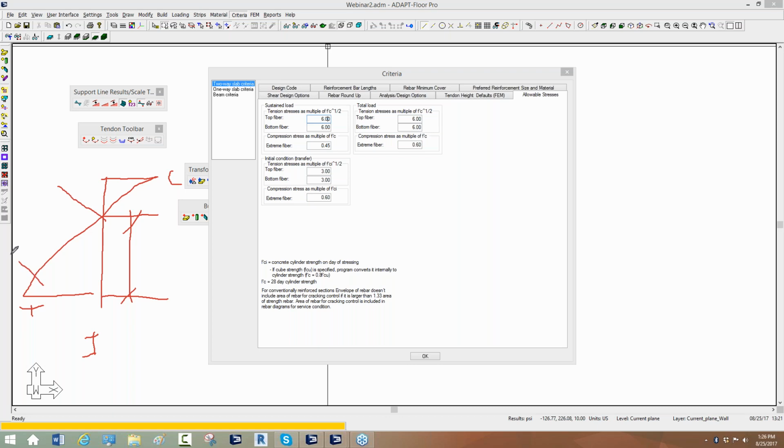So if you think of this in three dimensions, it takes this area times the width of the section to determine the tensile force in the block, and it takes that and takes the N sub c and divides that by 0.6 Fy, and this is hard to draw with this mouse, but that is the tensile force that it uses to calculate the rebar for the initial overstress condition. So the program will calculate it, it will envelope it as part of the overall reinforcement for the design of the slab.